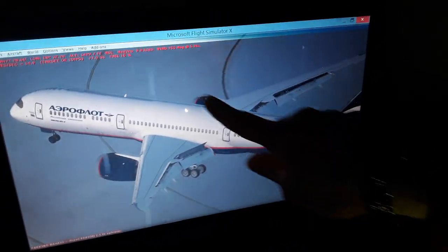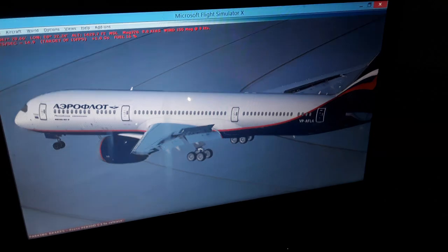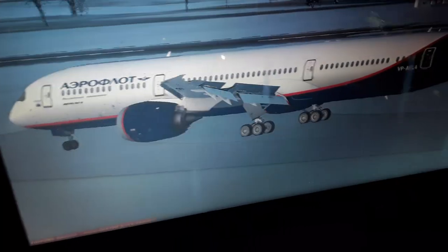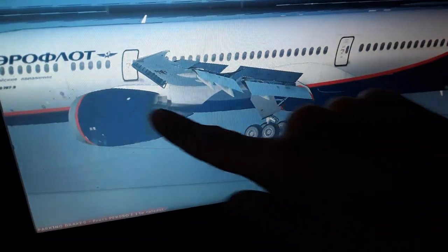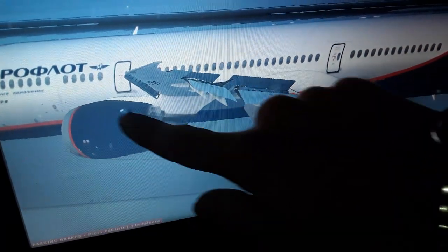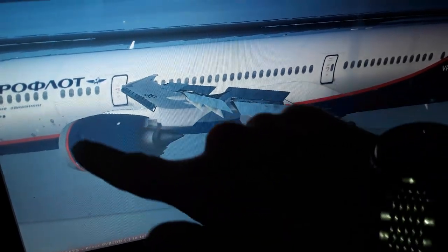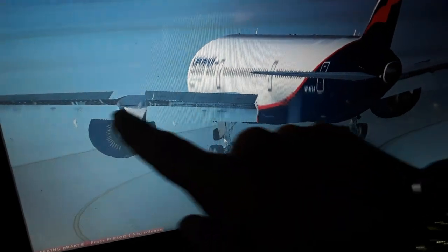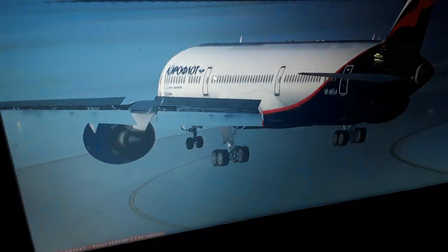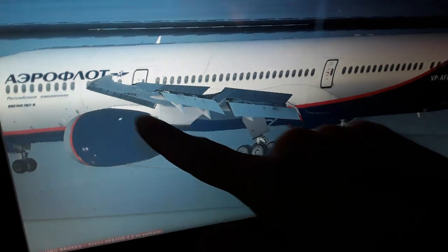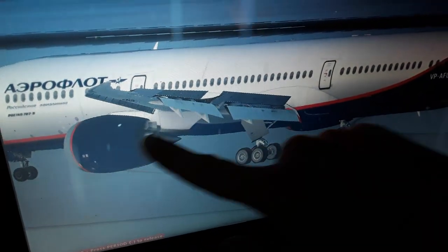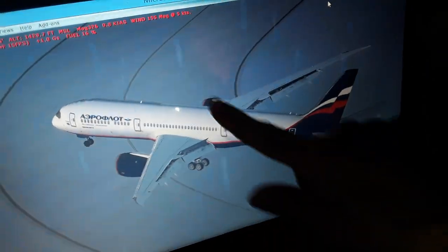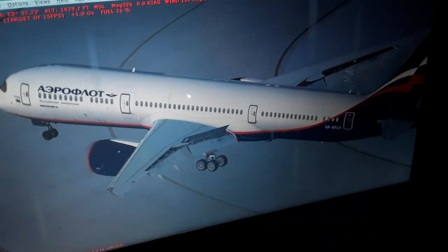So we have the thrust, these vectors from the engines, the jet thrust, because it's a jet aircraft. We have the high pressure compressor and turbine over here, the high speed starter and shaft, the low pressure compressor and turbine, the low pressure shaft, and the front fan. This is a jet turbofan engine. We have the fans here, and the bypass from the fan. And we have the high pressure section with the combustion chamber, and the exhaust that moves out as the jet blast of the jet engine. We have two engines for stability, on the left and right wings symmetrically.